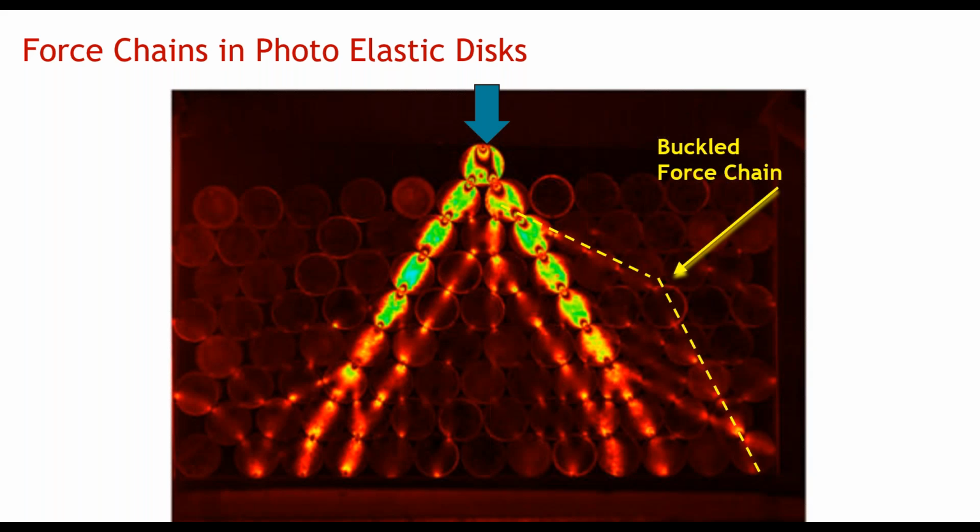If a force chain buckles, load will be shed to the next chain. The effect is that the remaining force chains are becoming more vertical and the loaded zone at the bottom is getting smaller, increasing stress on the base. This may lead to punching failure in a subgrade. As particles are being rearranged and displaced, the granular layer has less stiffness. This will result in the surface deforming or rutting.